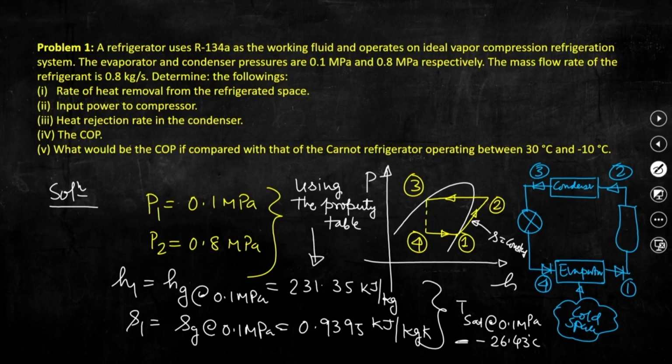Note that enthalpy at state point 1 you have already calculated. We are trying to calculate enthalpy at state point 2 by knowing the other two properties, and if we can calculate enthalpy at state point 3, that would be equal to the enthalpy of state point 4, because of the process that occurs in this device, that is the throttle valve.